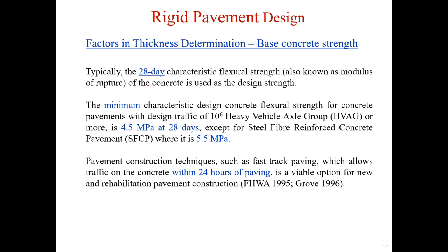But now, the next factor in thickness determination is base concrete strength. Normally, the 28-day characteristic flexural strength of the concrete is used as the design strength.